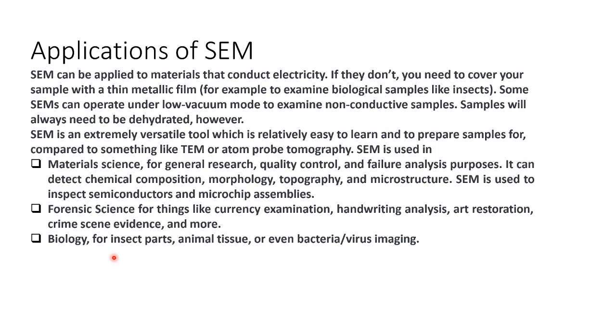If we want to observe a biological sample like insects, it has to be coated first before we put it in the SEM. Otherwise it will not give us a signal, because we need a conductive sample for the SEM. If we cannot coat some samples, then we have to go to the low vacuum mode. In those cases we can use biological samples, but even in low vacuum mode we have to dehydrate the sample. So normally biological samples we study in the ESEM only.